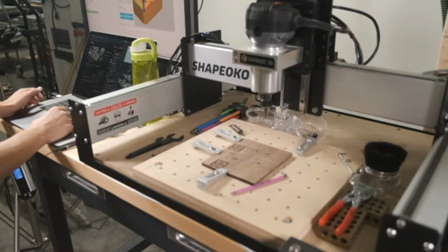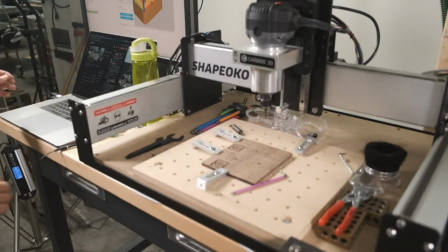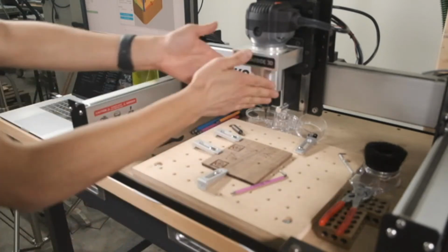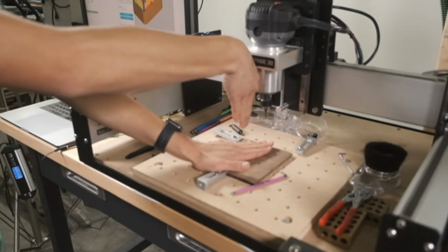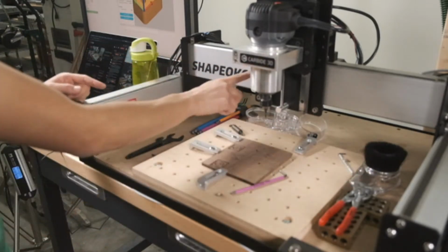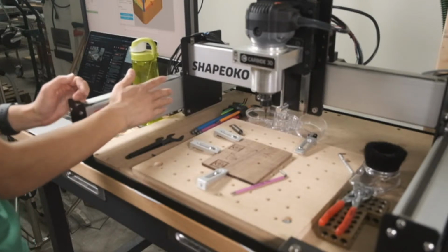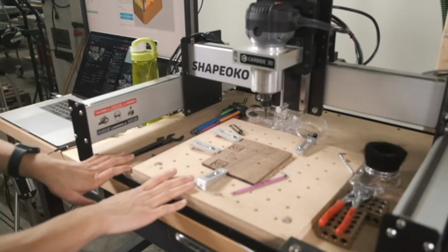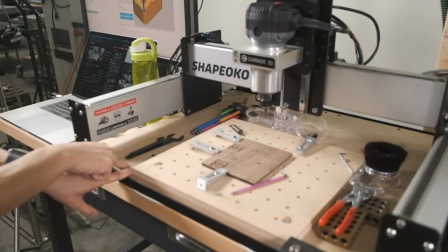Can I talk briefly about squaring the CNC? Sure. Tramming is specifically getting the spindle perpendicular to the wasteboard. Squaring is really about making sure that the X and Y are perpendicular to each other. The way the frame is designed makes the MDF an integral part of that process.